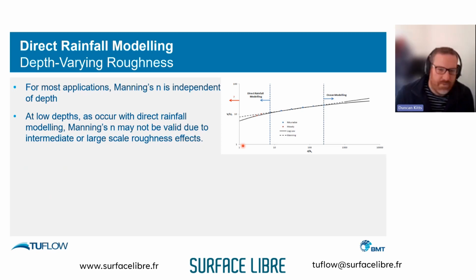That's when we consider millimeters of depth, and you think of your common bed resistance, the scale of that bed resistance relative to the depth of flow is quite similar, compared to when you've got deeper flow. The influence of the roughness height is much less.